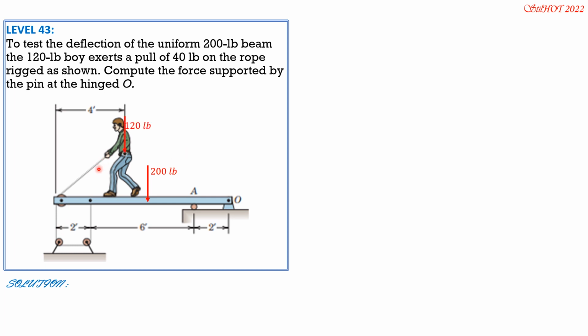And we have tension 40 pounds, so that will just cancel. This is also 40 pounds downward, and this is also 40 pounds downward. That's the effect of the tension on the beam. So reaction at A, NA, and reaction at O. So there's no horizontal component of reaction at O. It's downward, expected downward, because the tension will just cancel. This 40-pound force will just cancel.